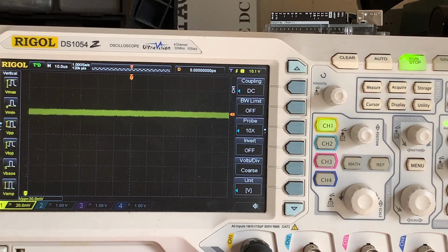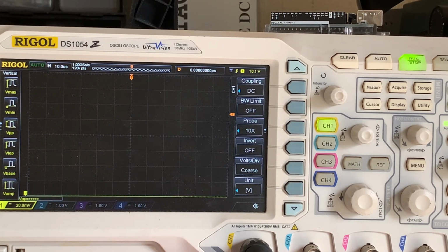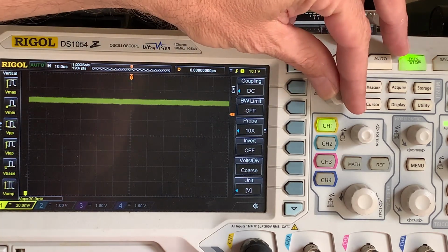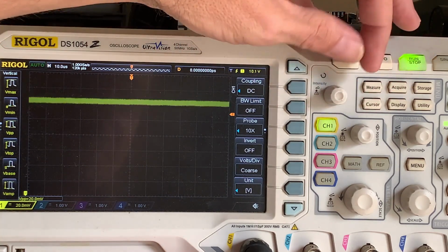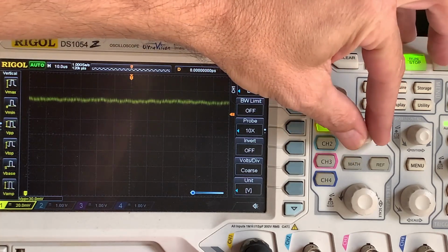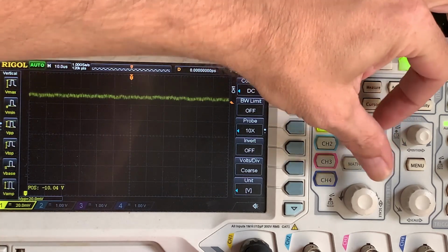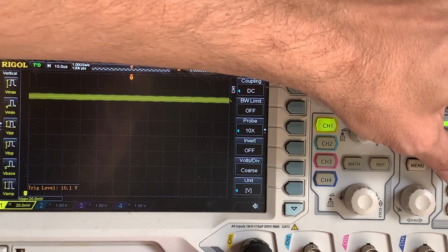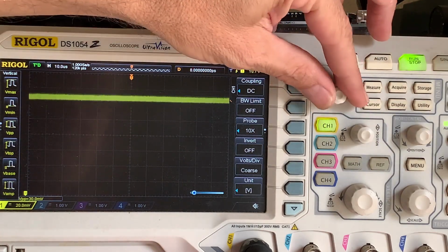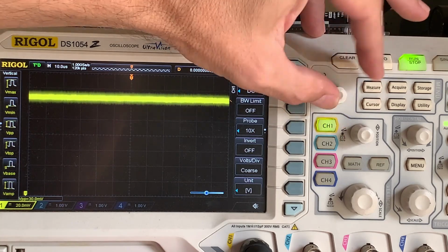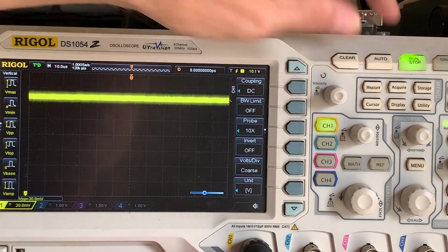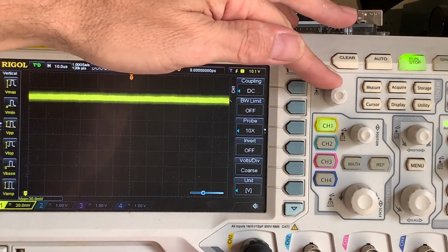Now I'm going to go to the base of the second of the double transistor, or the circuit with the feedback, and you can see same sort of thing. The amplitude of the base voltage is more. Okay, so let's see if I do it like that. Will it help? No. So you can see that snaky sort of thing going on in there.